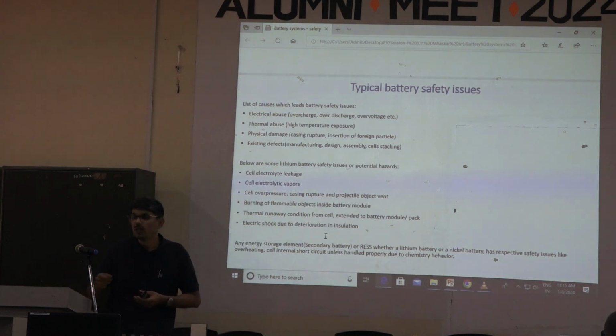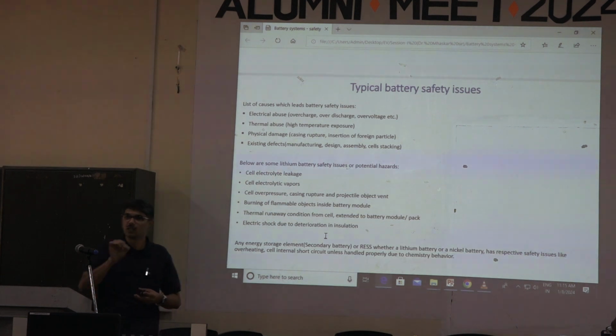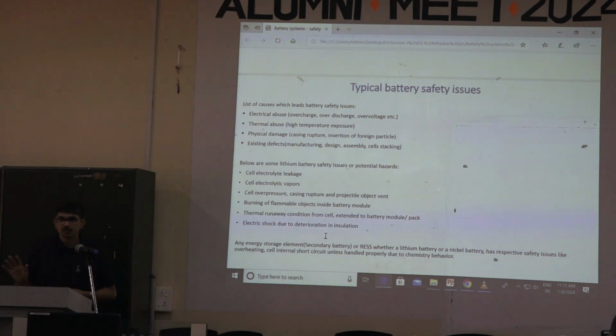No one goes, yes, in India it is not yet, but no one goes and says please charge the vehicle. It is like you connect the charger, your wallet gets automatically debited as soon as you connect the vehicle. So if you want to go into that mode, go and see plug and charge, you see Open Charge Protocol, OCPP we call it. So just have a look at it, you will realize people have already advanced to the next phase where it is like what we do in UPI, same can be done in the charger.